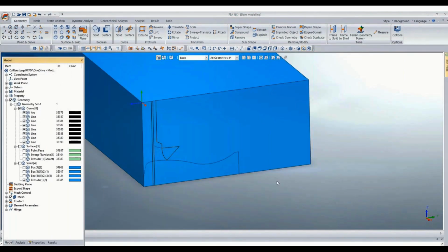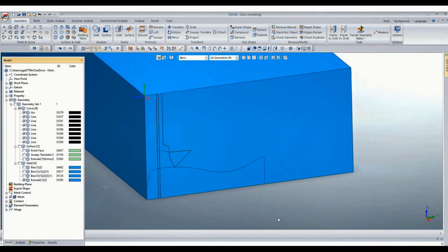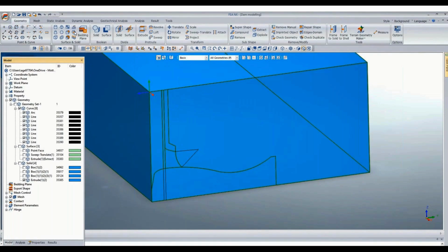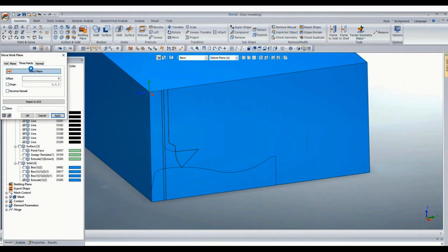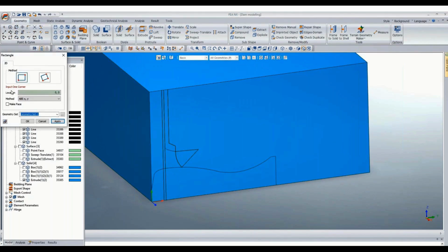Okay, now let's create a trunnion beam, profile of trunnion beam here first. So for that, what I'll do, change my work plane to this plane, create a rectangle, make face. From here, say length is 4.5 meter, comma, say 4 meter is the depth of the beam.